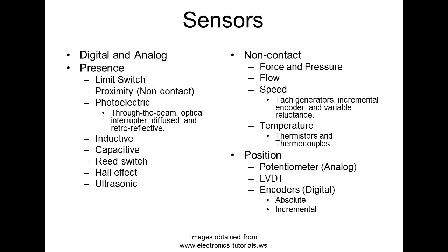Because it doesn't alarm all day long, and it doesn't change volumes, it doesn't do anything like that. What does it do? It goes off at a certain time. And the alarm is either on, or the alarm is either off. That's digital. Now, it doesn't mean we can't change when the digital switch occurs. We call it a threshold. So most of your sensors give you the ability to set what we call a threshold, so you determine what is true and what is false.